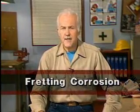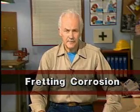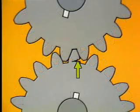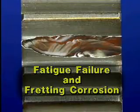Fatigue failures of gear teeth usually occur over a lengthy period of time, and they may be accompanied by what's called fretting corrosion. Fretting corrosion is set up as the gear tooth is loaded and unloaded. As the tooth is loaded, lubricant seeps into the defect and is compressed each time the tooth leaves its mesh. The combination of oil, high pressure, and a slight tooth motion breaks the metal down in the crack and erodes it. A reddish stain is produced as the metal breaks down. When a tooth breaks from a combination of fatigue failure and fretting corrosion, the break area will have a reddish stain.